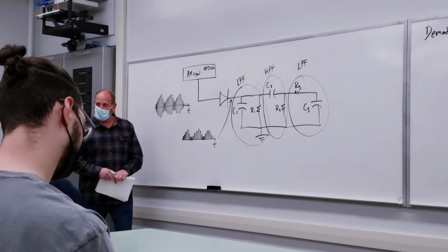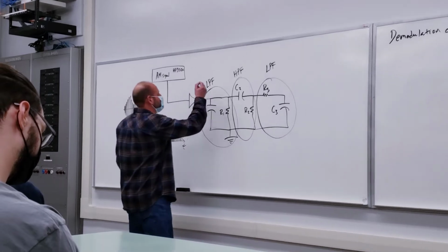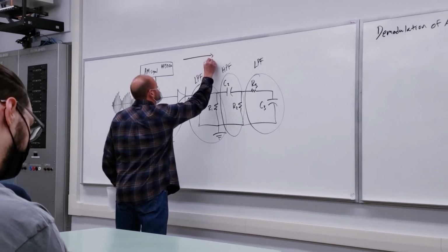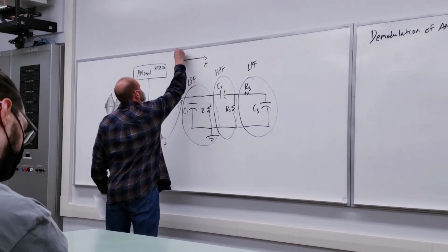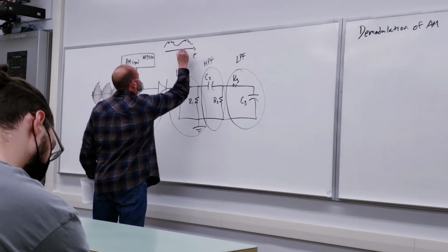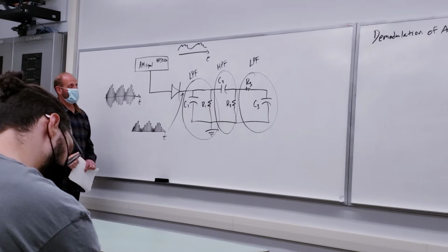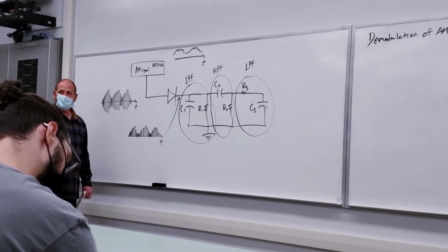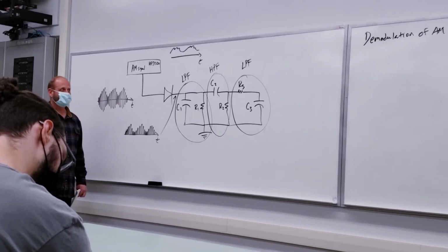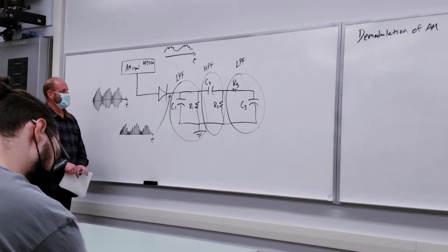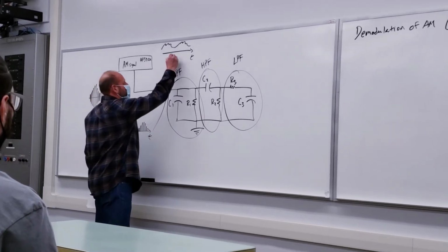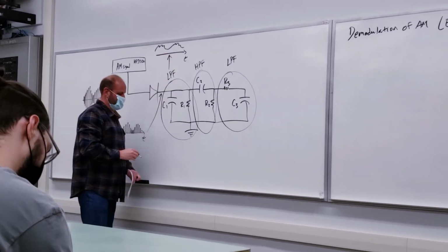And you can only do so well with a first order filter, so you're going to get something that looks like this, where it's kind of wiggly, but you can see something sinusoidal. We're not following the carrier, but we're not really having a good sinusoid yet. So that's the picture we get out of stage one here.